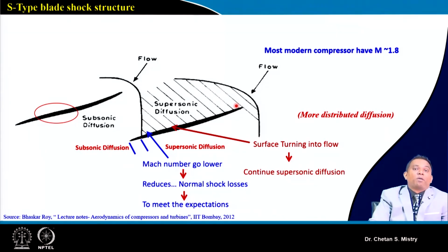Then we were discussing our stall margin. In this case, the margin for stall will be less when we are discussing the transonic aerofoil. So you can say my flow incident, my leading edge, is very sensitive to the change of incidence. We will be discussing all these terms again in detail also. Now here we have seen we are having a steeper kind of characteristic. This steeper characteristic has come because of this particular shape of aerofoil.